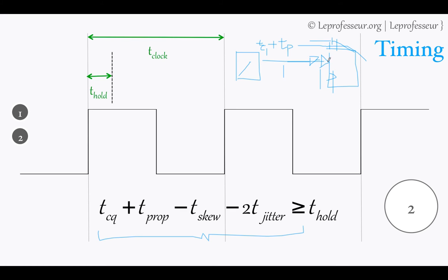Simply insert the buffers so that this delay is more, so you are basically increasing the propagation delay. Now if you insert the buffers, it may disturb the setup time requirement, so it's something you have to play around with. Nowadays there are EDA CAD tools, say PrimeTime, the industry standard tool which does the timing checks for your digital design.